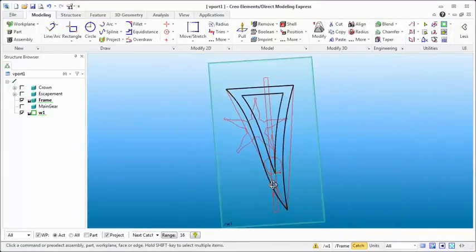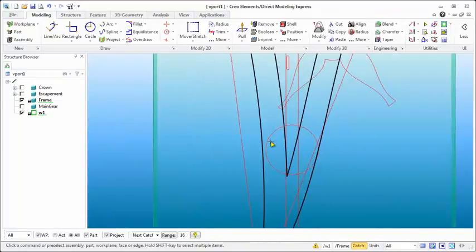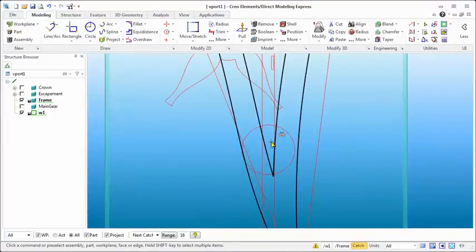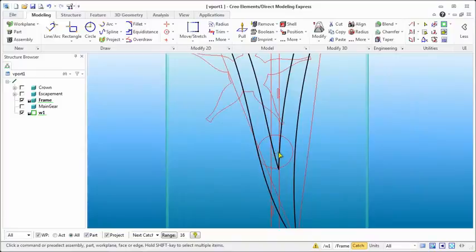One thing I do notice here is that I want to be able to have an axle right here, but the problem with that is, well, let's just get this view into a better position. The problem with that is that the center of the axle will come in here, so I kind of need to create a fillet in here. Now I can come in and create a radius using some of the 2D sketching functions that you have here, but generally I like working in 3D, maybe create the fillet that way.